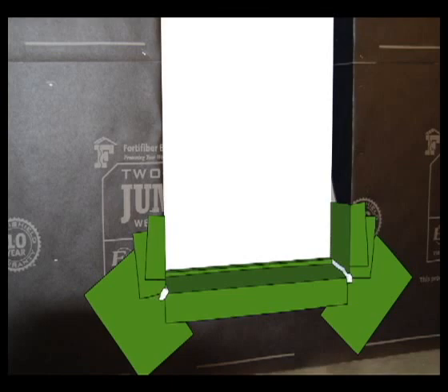This picture shows the bottom of the window rough opening pan flashing detail. A pan flashing is an enforced code requirement in a number of states. The window rough opening pan flashing can be fabricated from a variety of waterproof material and is commonly available in prefabricated units. Pan flashing is installed over the WRB materials that are commonly wrapped in the window rough opening.